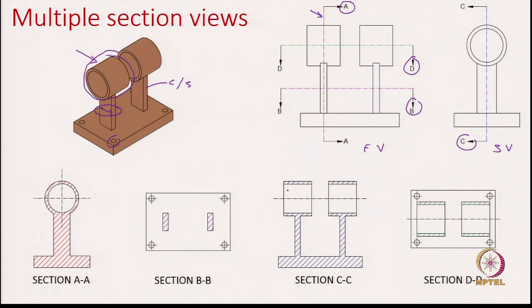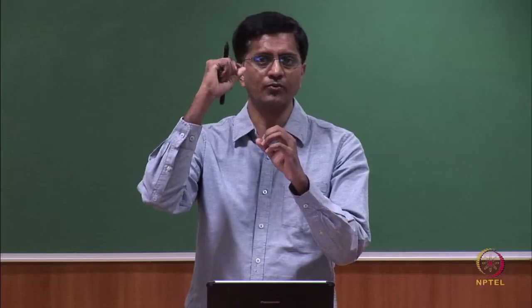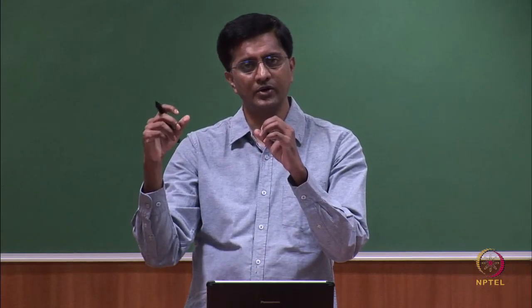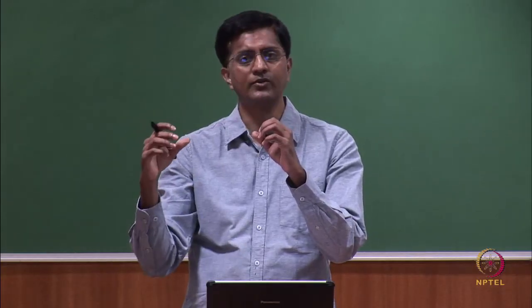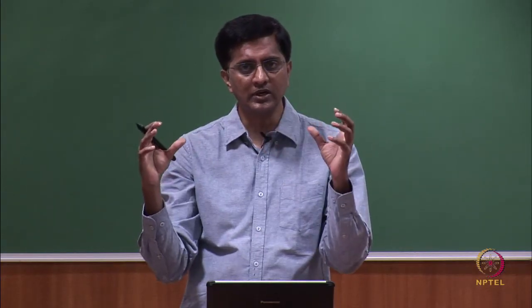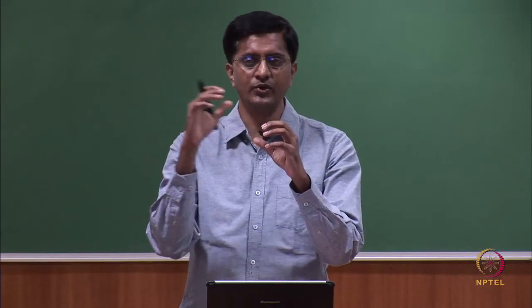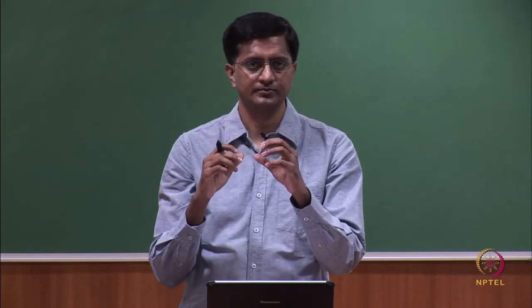So, here you see that the alignment of the views is different. Previously, we had perfect definitions for alignment when we were drawing the multi views, right. We said depending on first angle or third angle projection, if it is a third angle projection, your top view is placed above the front view, and the left side view is placed to the left of the front view. So, these are perfectly oriented views where we say where to place the front view, side view, top view.